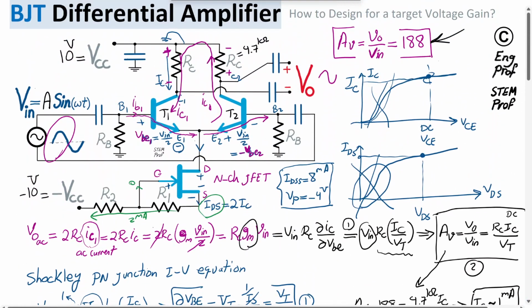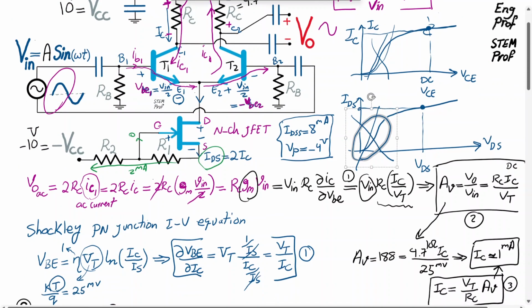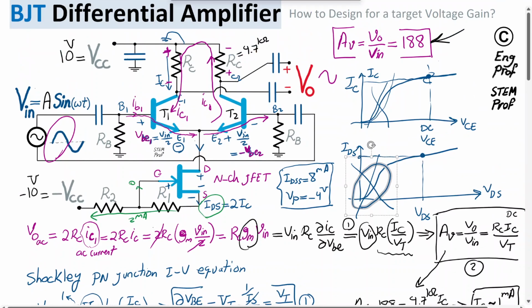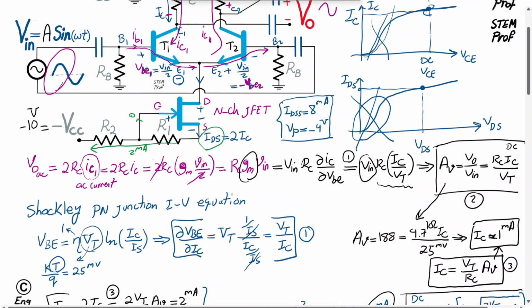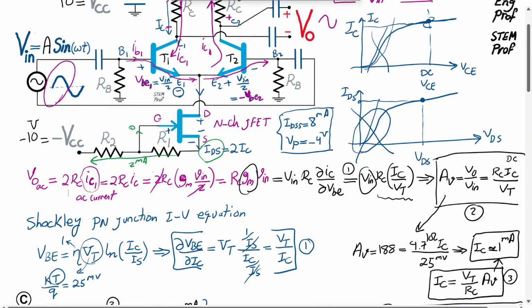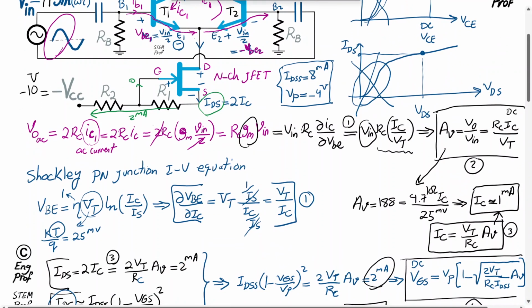Great. So R1 known, and the DC bias of the two transistors, the BJT transistor and also the JFET transistor, is known. One other thing I can quickly find is RB, but I can get to it last because it's a minor thing to find. Regarding R2, it's important to make sure that, as I said, the N-channel JFET is properly biased in this region. And in order to be in this region, not in the ohmic region of the JFET or linear region, we need to make sure that the drain voltage is higher than the gate by the absolute value of pinch off. So that is an absolute requirement.